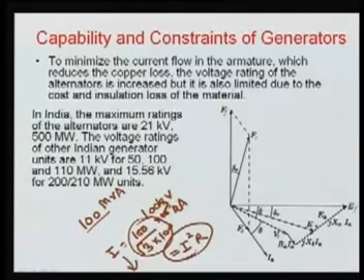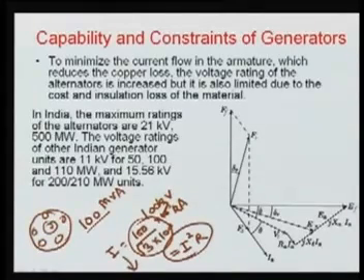If you go for increasing voltage, in any alternator, here this is your armature with the different windings at the stator, and here we have the rotor that is rotating. If the winding is operating at 100 kV and the outside shell is at ground potential, then we have to provide an insulation level for this higher voltage.